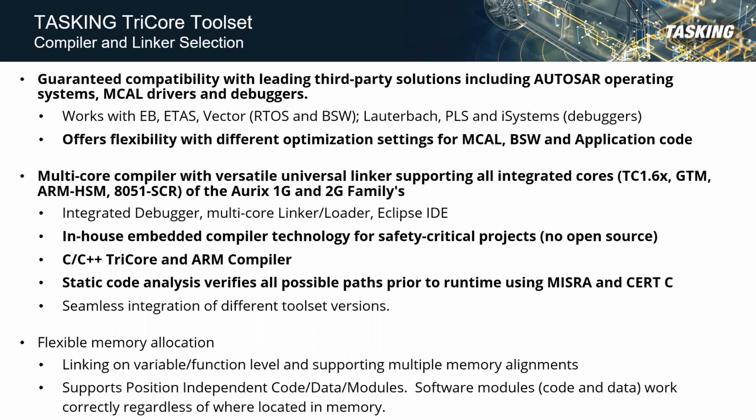One of the other features of the Tasking toolset is that it's a multi-core compiler with a versatile universal linker, and it supports all of the cores that are integrated in the AURIX. So the AURIX has the performance cores, as we've talked about. There's a generic timer module core. You have an ARM-based core in the HSM module. You have an 8051 in the standby controller.